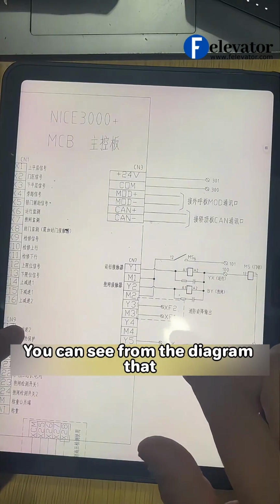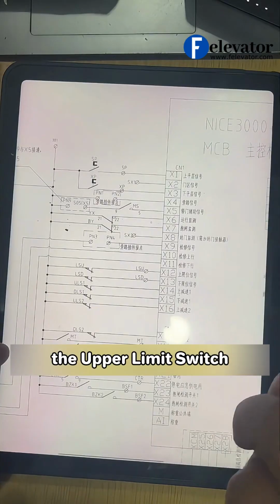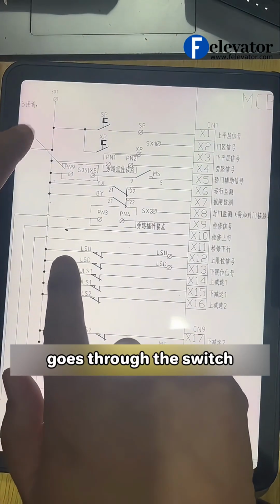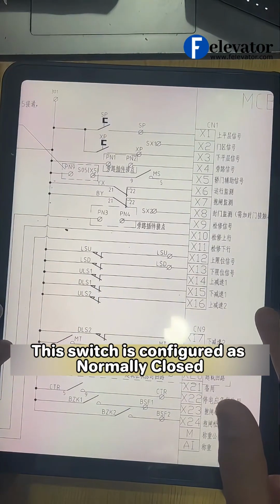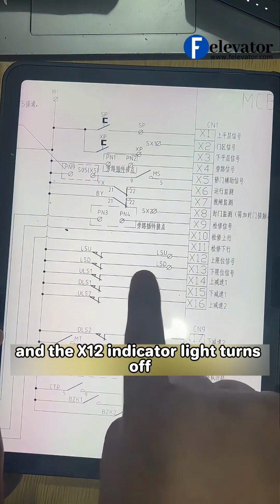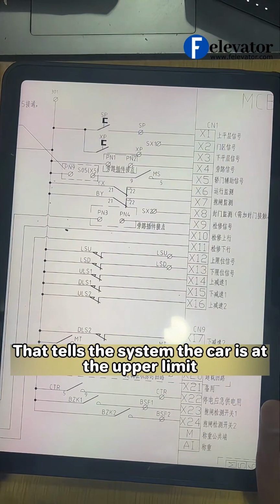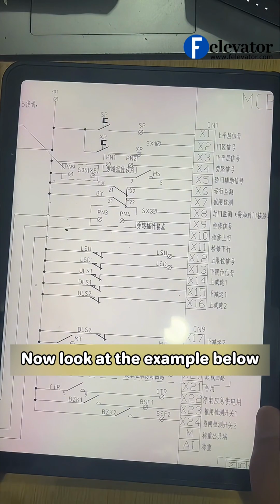You can see from the diagram that, for example, the upper limit switch signal comes from the common line 301, goes through the switch, and finally reaches X12. This switch is configured as normally closed. When the elevator reaches the upper limit position, the switch activates, the circuit opens, and the X12 indicator light turns off. That tells the system the car is at the upper limit and should not be allowed to travel any further up.